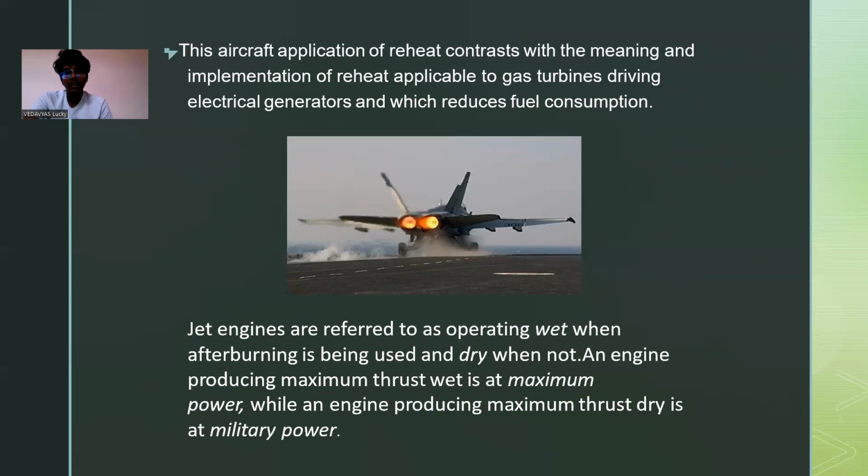This aircraft application of reheat contrasts with the meaning or implementation of reheat applicable to gas turbines driving electrical generators, which reduces fuel consumption. Jet engines are referred to as operating wet when afterburning is being used and dry when not. An engine producing maximum thrust wet is at maximum power, while an engine producing maximum thrust dry is at military power.